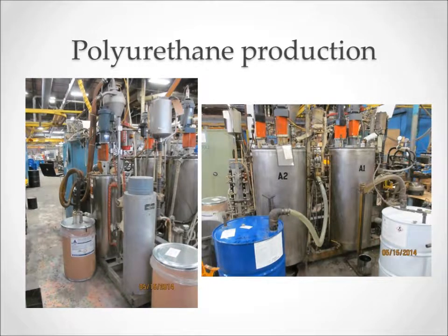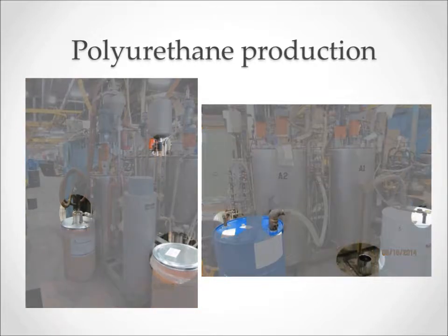In this type of system, the exposure potential is reduced to a few areas since most of the operation is automated. Areas to check for contaminations include the hose endings going into the drums, the floor beneath transfer hoses in case of any cracks or leaks in the line, and the tops of drums in case of spilling or splashing during removal of the lines.